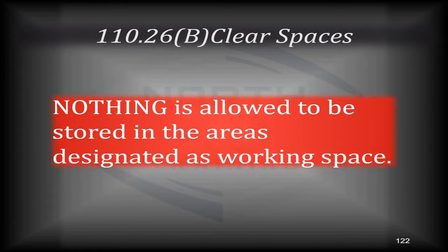This is probably one of the least favorite portions of Article 110 for most electricians. It allows people to store stuff in the area that has electrical equipment. 110.26(B) says nothing is allowed to be stored in the areas designated as the working space.